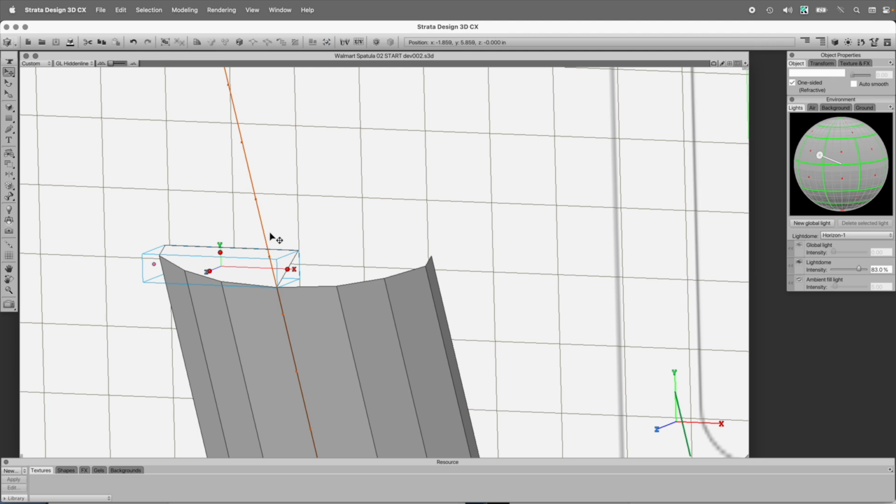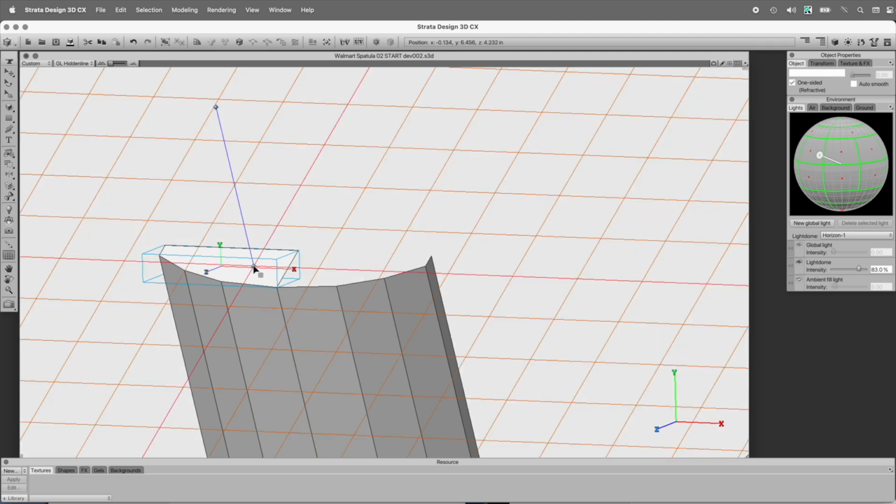So we can do something kind of clever. Let's come back over to the grid tool, click on that face, and it establishes a temporary custom active grid, and then anytime you create a new object, it's going to be based on that grid. So if I create just this plane right here, I'm holding the shift key down to constrain its size.